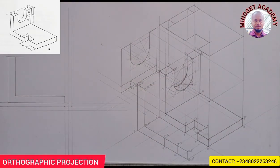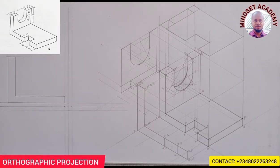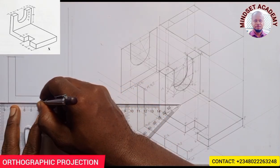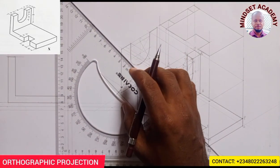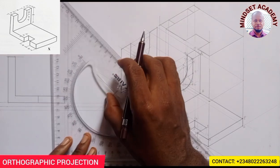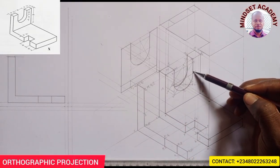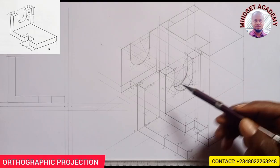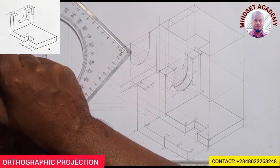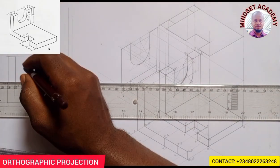And we say that from our diagram, from here to here is 20. And from here to here is 20, which is making 40, right? So I'm going to measure 20. So from here, 20, then to 40. So I'll draw my vertical line on that part. Then the next one, from here, we'll measure 20, then 15. That is 35. So I'll measure 35 downward, 0 to 35 here. So that point will be where my hidden line will be.